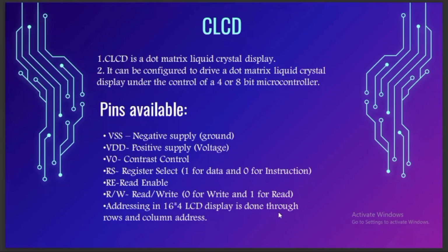CLCD. What does CLCD stand for? CLCD stands for Character Liquid Crystal Display. Generally, we all know what an LCD is, but what is CLCD? CLCD is a dot matrix liquid crystal display. It can be configured to drive a dot matrix liquid crystal display under the control of a 4 or 8-bit microcontroller. And in this CLCD, many pins are available. We can see some of the pins over here.